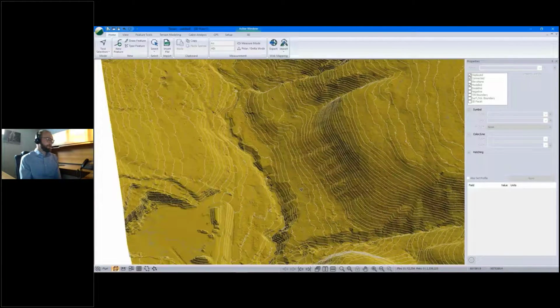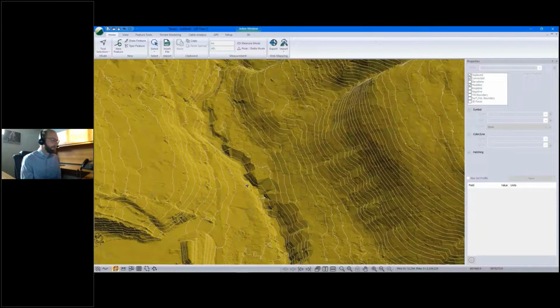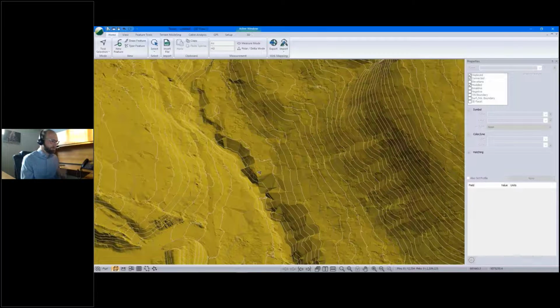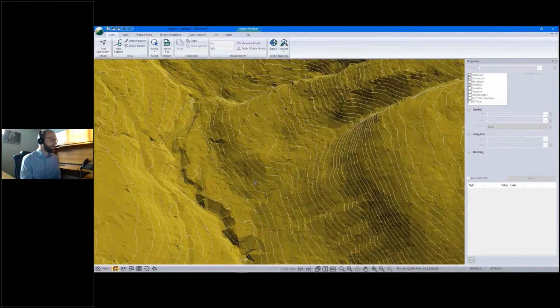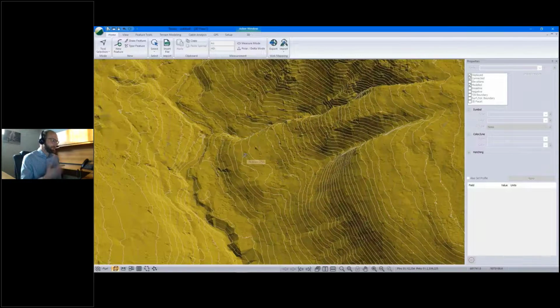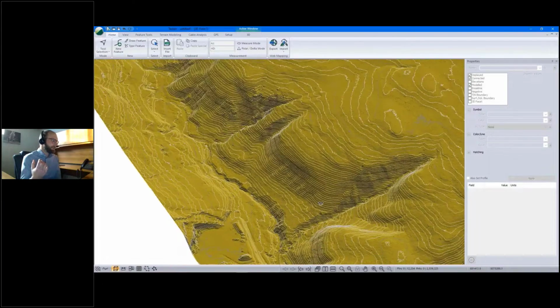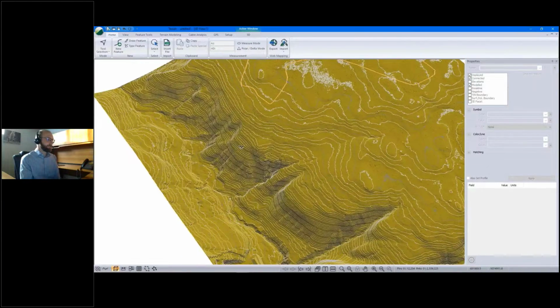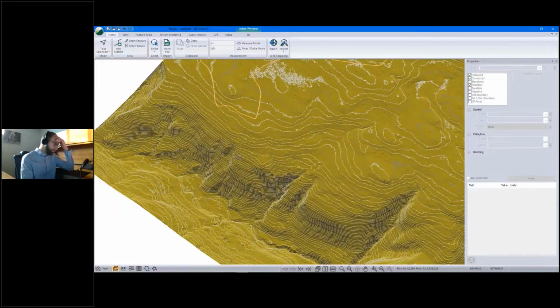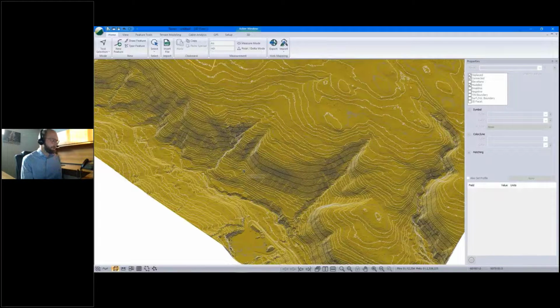Once I'm happy with that landscape level, I'm going to zoom in and look at my critical areas. And again, I'm going to just keep evaluating, okay, does this surface look reasonable? Should I check it out with closer detail when it comes time to field truthing? And for critical areas, I'm going to include things like intersections, crossings, switchback locations, and any steep, complex terrain. And if you're in flatter terrain, it'll be looking at ridge tops or low points where you expect to place that road.